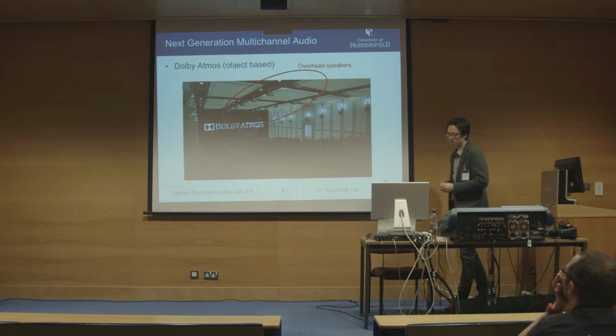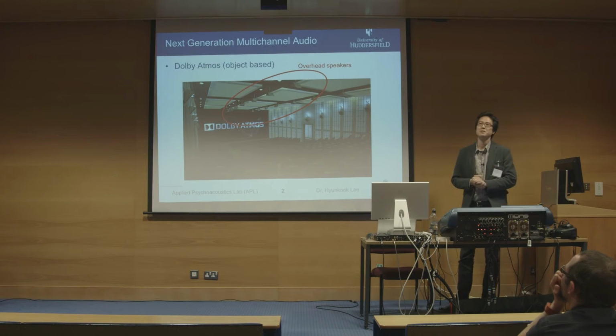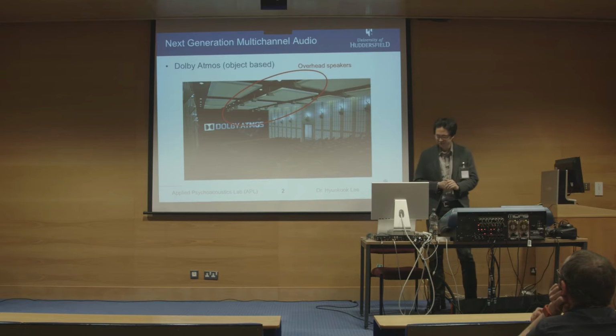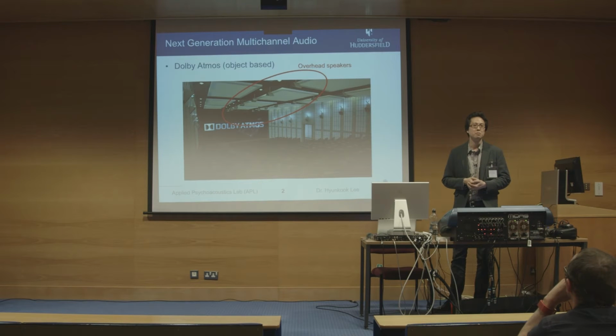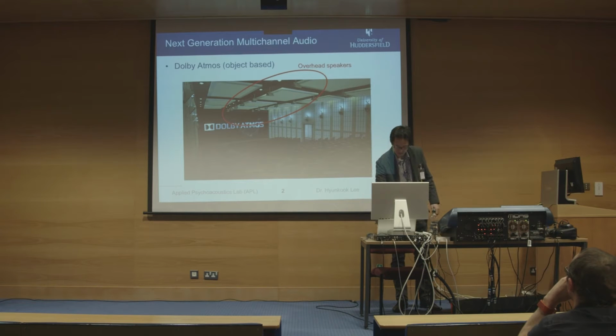Channel-based audio is limited in terms of reproduction system layout, because in a recording studio, if you produce the music using a 5.1 surround loudspeaker format, and listeners have a different loudspeaker format, then the original intention of the producer will be ruined at the user end. But with object-based audio, you can recreate the directional information of the original mix as similarly as possible, because you're relying on the metadata of each object's direction.